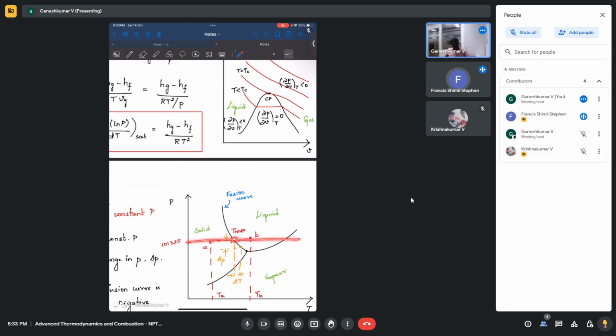But when we are looking at that steam table, we will only have one P saturated, isn't it, corresponding to one pressure. So in steam tables, it's always about liquid-vapor conversion. Okay, sir. So it focuses only on this part of the curve.